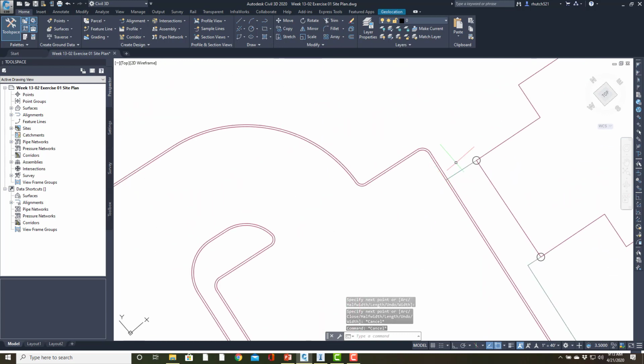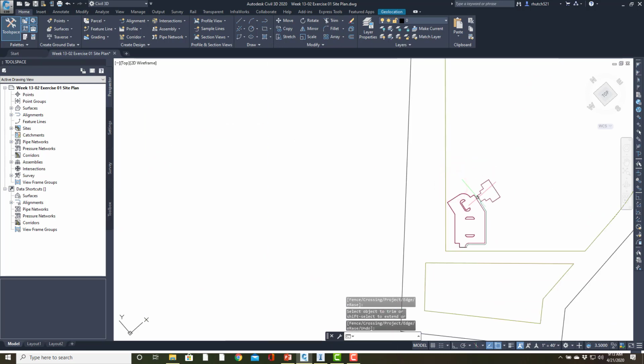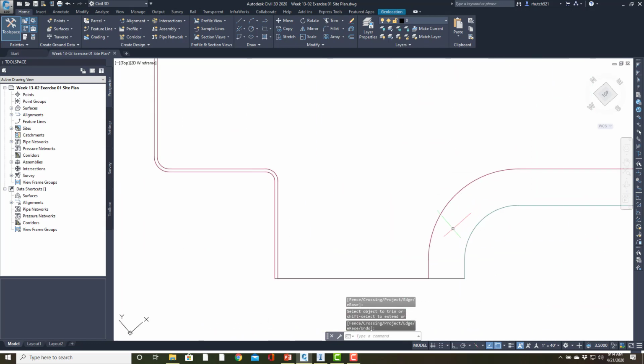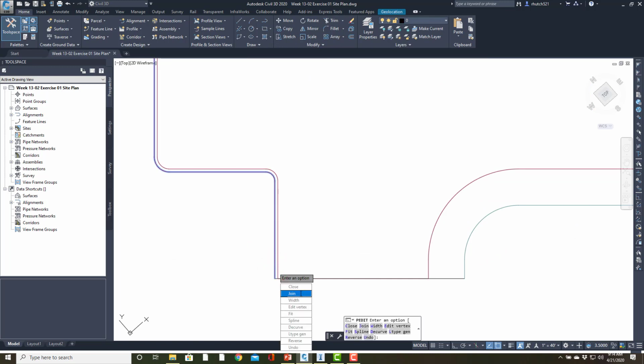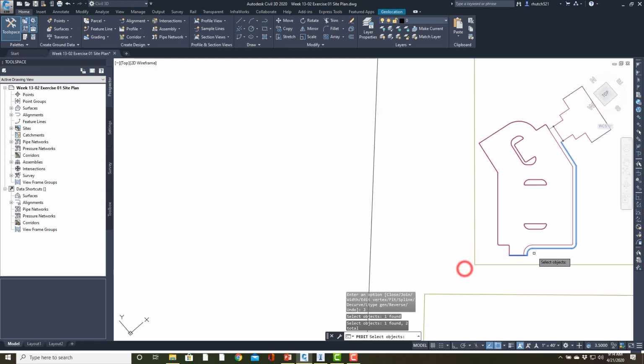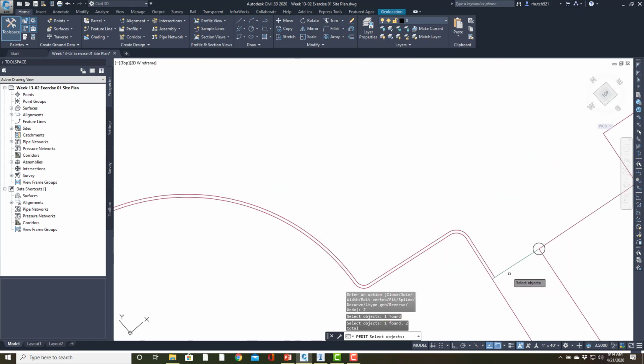And then I'll just trim this out over on this side because this is all going to look like concrete, so I don't really need the curb edge here. I'm using the sidewalk. So I'm going to hit enter, get rid of that. There we go. And so now I have a nice little area, and I can just use the join command. So double click on that, join, and join this to this, click that. And now what I want to do here is let's fill this 0.